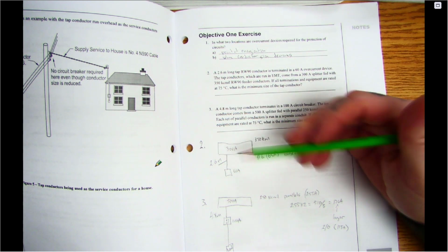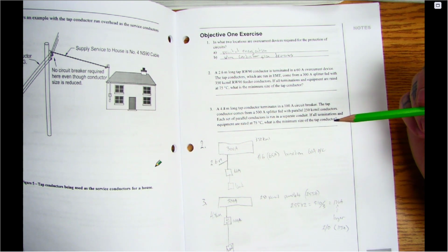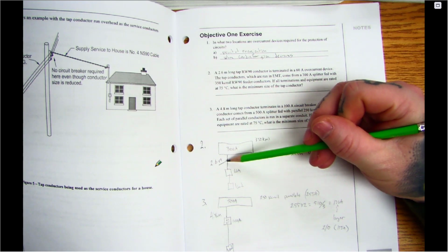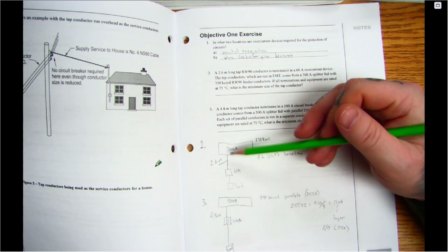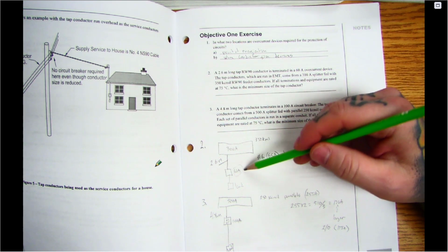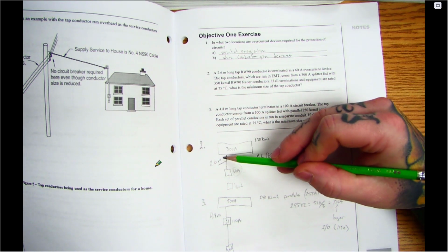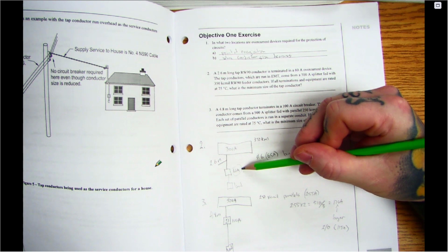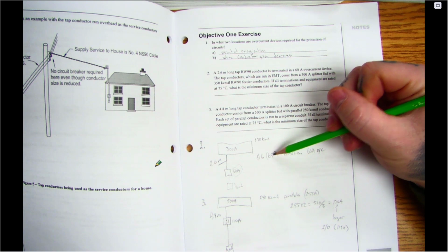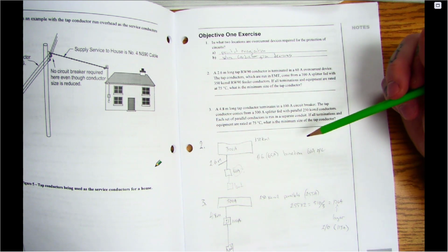What we have to look at, again, is that we would have a load down here as well, but they haven't told us about that. We don't need to know, in all fairness. If this is 3 meters or under, just like in that example, we use the rating of the overcurrent device or switchboard, panelboard. So that's what we're going to use in this case because of this length. We can just use the 60 amp from the overcurrent device and size a wire based on that. So we use a number 6, which is good for 65 amps based on that 60 amp overcurrent.